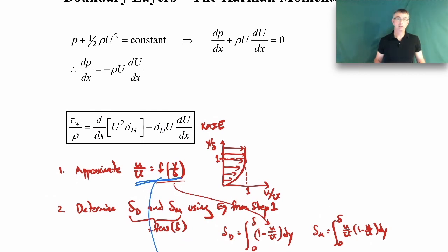And we use this technique again to figure out expressions for turbulent boundary layers or boundary layers with some sort of pressure gradient, or where the outer flow velocity isn't a constant, where it varies. And so that's how we use this equation. We'll use it specifically in this course to get the turbulent boundary layer expressions. But I give a couple of examples in separate videos where I actually apply this a few different ways. I think we look at a parabolic velocity profile as an approximation to a laminar boundary layer, just to check how close we get to the real Blasius solution.